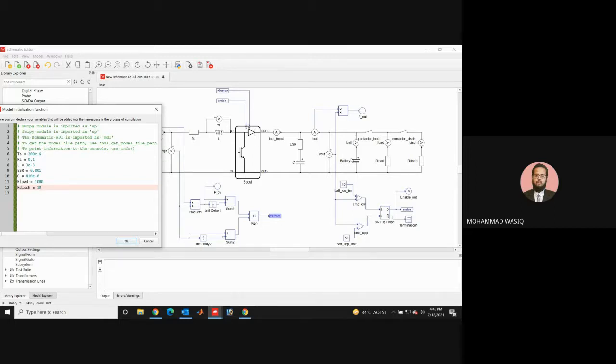Sir, please explain again. See, over here we have taken two comparators and we have set limits. One is 49 and the other one is 52. Now see the logic of the SR flip-flop. Let's take an example: we are measuring the output voltage as 48, which is less than 49. So 49 minus 48 is 1 over here, and for 52 we are getting 0 over here. So here we're getting 1 as output.